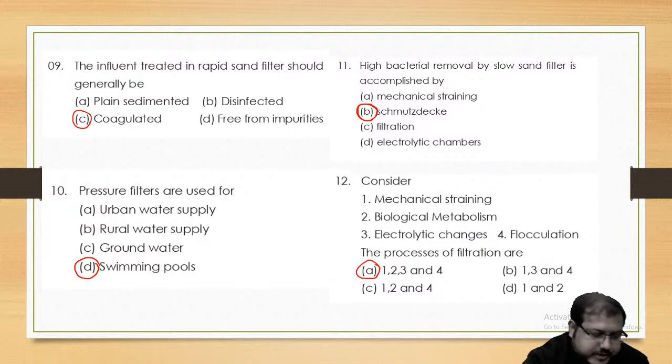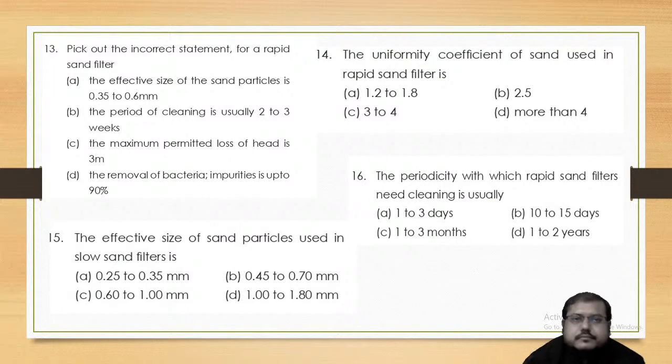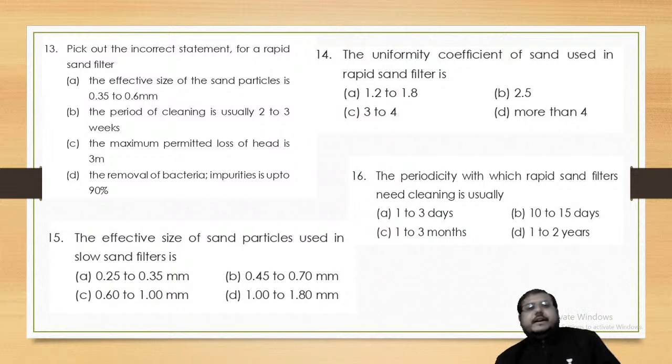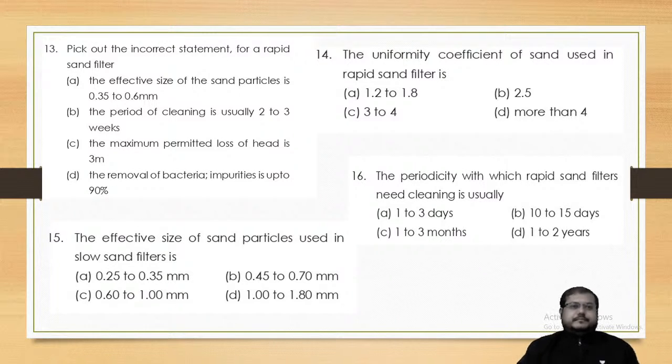Let's go for question number 13. Pick out the incorrect statement for rapid sand filter. The effective size of the sand particle D10, it's true, it's correct. The period of cleaning is usually 2 to 3 weeks. No. Once in a day or in 2 days. So question number 13B.